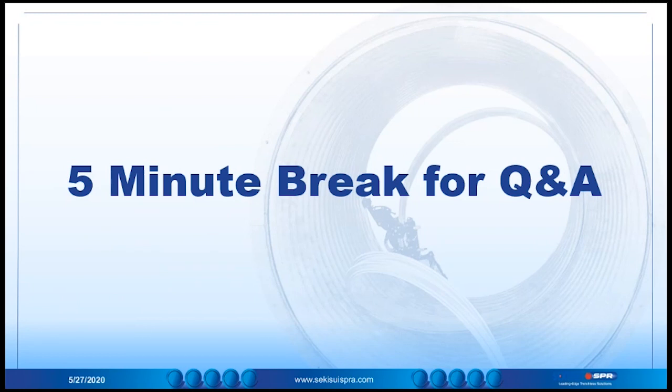Great, thank you, Jackie. And we were just talking about installation in live flow. When would it be necessary to include flow bypassing? Can other flow management options be considered as well? Sure, absolutely. Spiral wound liners can typically be installed in live flow, up to 30% full pipe with smaller diameter rehabilitation, and 20 to 25% with larger diameter rehabilitation.